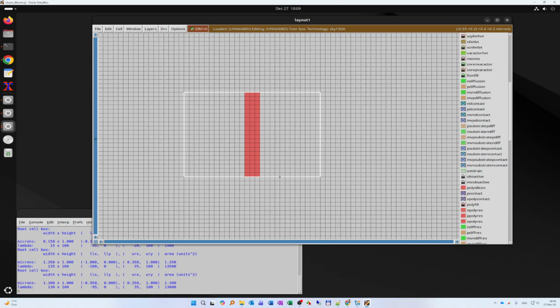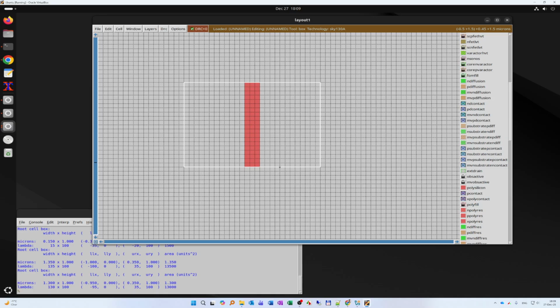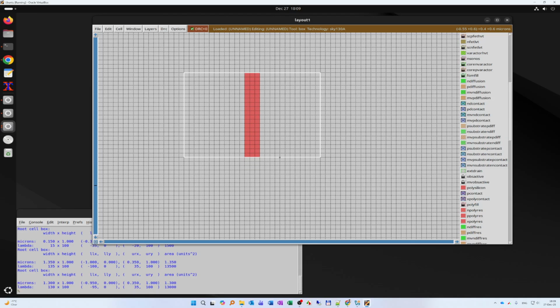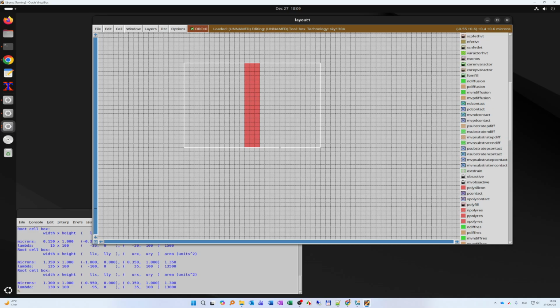For the serious layout, we should do the same space on the left and the right, but for this tutorial, we just need to familiarize ourselves with the process. So I'm not going to go into too much detail. I'm just roughly drawing the layout, and we're going to go through all the layout process. And then we can choose N diffusion, middle button, choose the N diffusion.